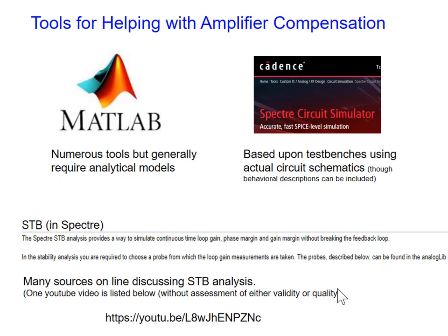Open loop DC gain doesn't tell us much at all about stability, or about time domain performance. If you put ridiculously big components in, you might get fantastically good results. You just put a ridiculously big compensation capacitor in, and everything would appear to perform well. If it's sluggishly slow, it would appear to perform well when the real system won't.